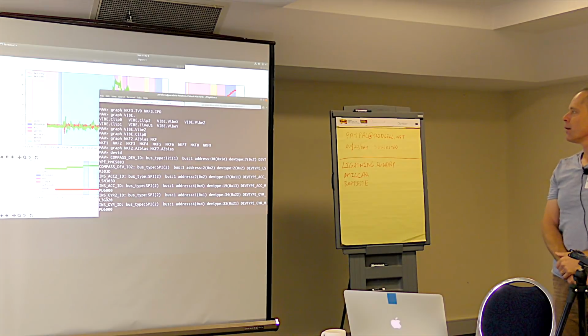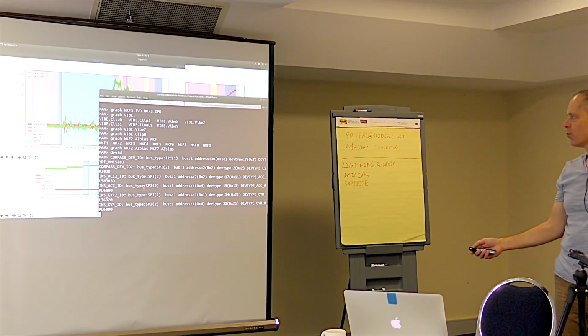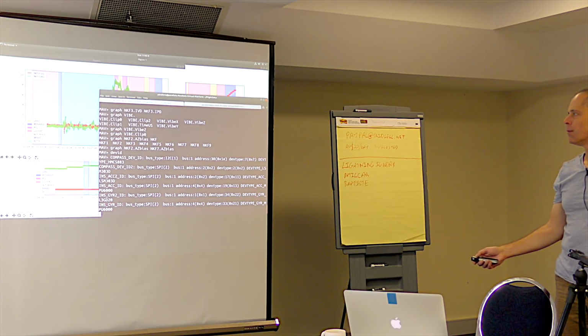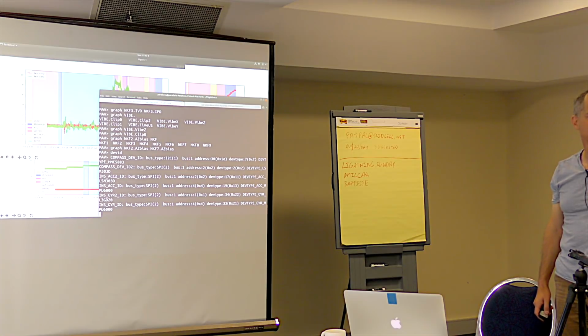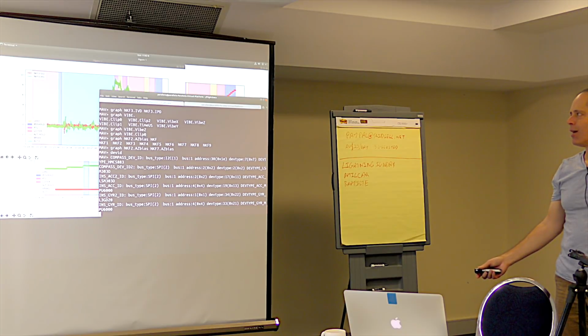The first accelerometer. Yeah. So that's SPI2, it's an MPU 6000. Yes, that's the first one. Unfortunately, we also mapped one of the ICMs onto MPU 6000. We didn't differentiate, the same driver. That's only for compass, isn't it? No, we do that with one of the others. Most of the ICMs are broken out. There are two types that map to MPU 6000. Plus 6050 is mapped to the same. Yeah. So, I mean, these are rare occurrences, but they're not unknown.